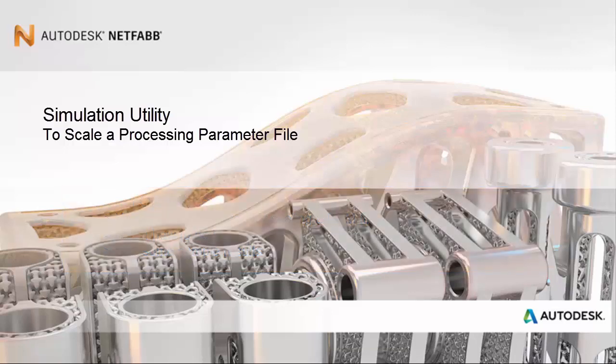Let's assume for this exercise that we have run several test prints of a part using the Inconel 718 material and measured a peak distortion of 0.4 millimeters along the external face. We're going to simulate this build in Netfabb simulation utility and see whether the simulation results are close to the experimental results. If not, we'll know that the PRM file we used is not going to produce accurate results in other simulations with Inconel 718. To correct this issue, we can scale the PRM file and see whether it will produce displacement results more in line with actual test results.